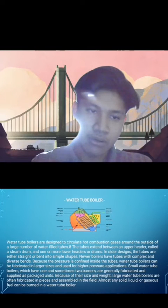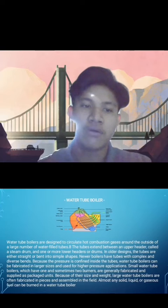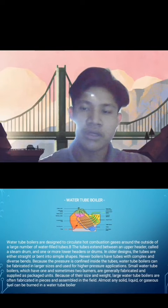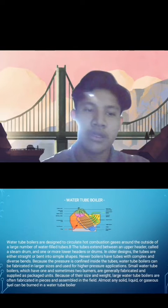Water tube boiler. Water tube boilers are designed to circulate hot combustion gases around the outside of a large number of water-filled tubes. The tubes extend between an upper header called a steam drum and one or more lower headers or drums. In older designs, the tubes are either straight or bent into simple shapes. Newer boilers have tubes with complex and diverse bends.